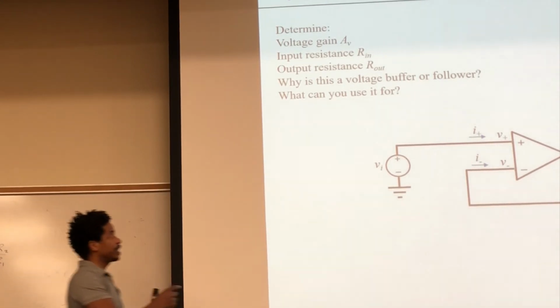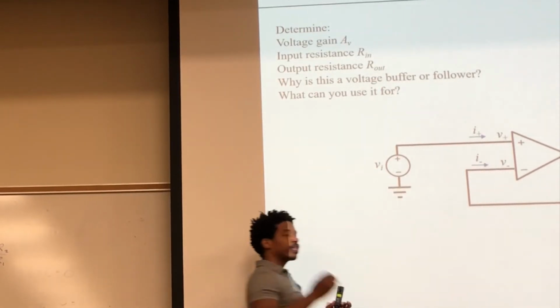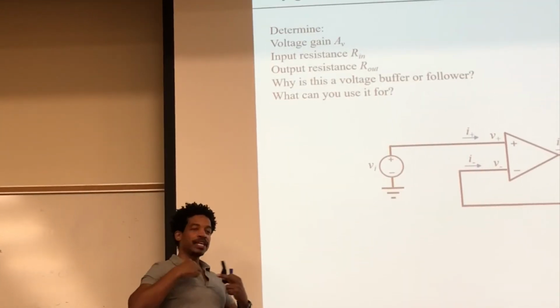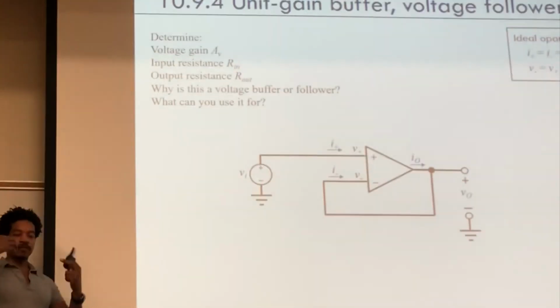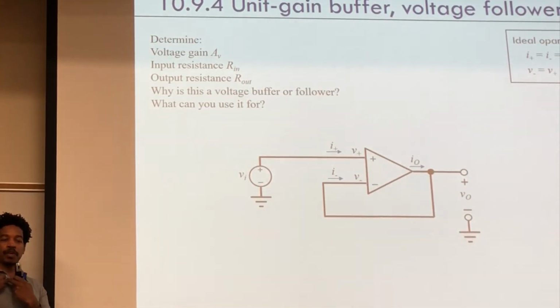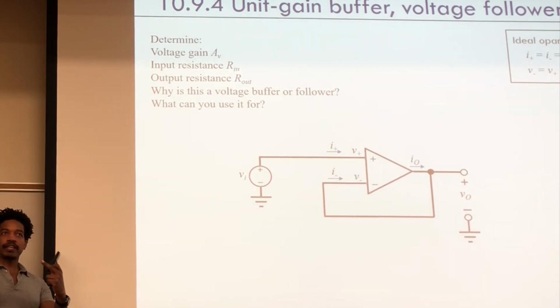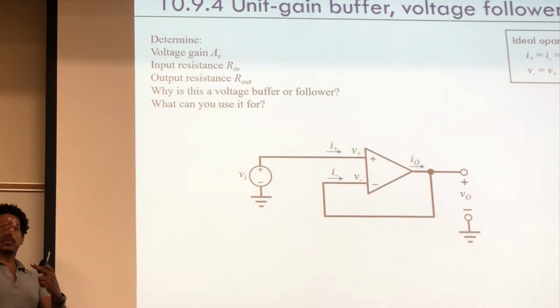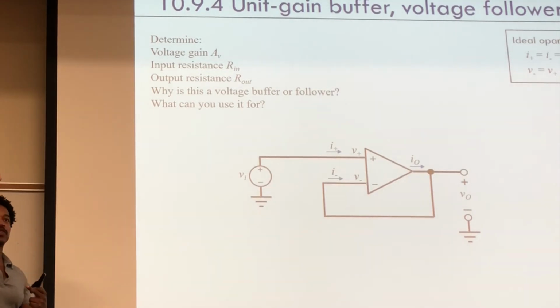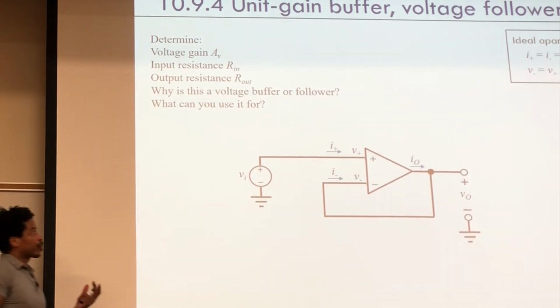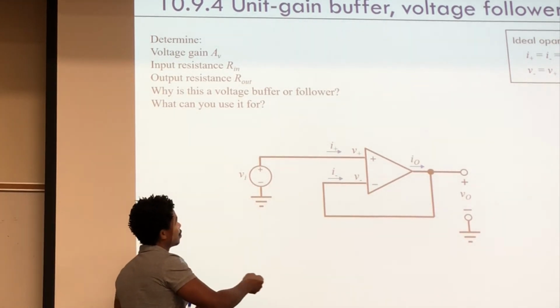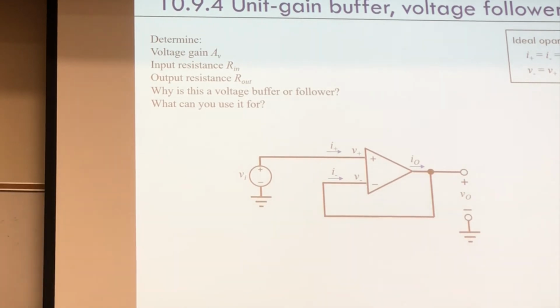If you had a very sensitive voltage sensor that could sense points in the air from me to you, you would see that if you touch my body, 10 volts, but a little further away from my body there's a field that's 11 volts, then 12 volts, 13 volts, until I get to your body, and if I touch that probe to your body, it'll eventually be 20 volts. But you don't want to disturb your experiment. That's why you would use this buffer, this voltage follower. This copies the voltage, but doesn't disturb anything.